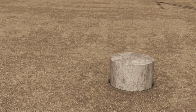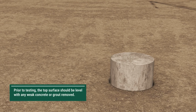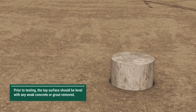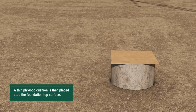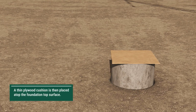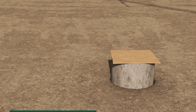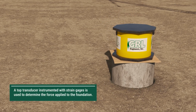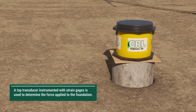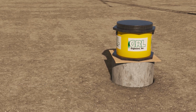Prior to testing, the top surface should be level with any weak concrete or grout removed. A thin plywood cushion is then placed atop the foundation top surface. A top transducer, instrumented with strain gauges, is used to determine the force applied to the foundation. The top transducer is typically attached to the foundation using anchors.